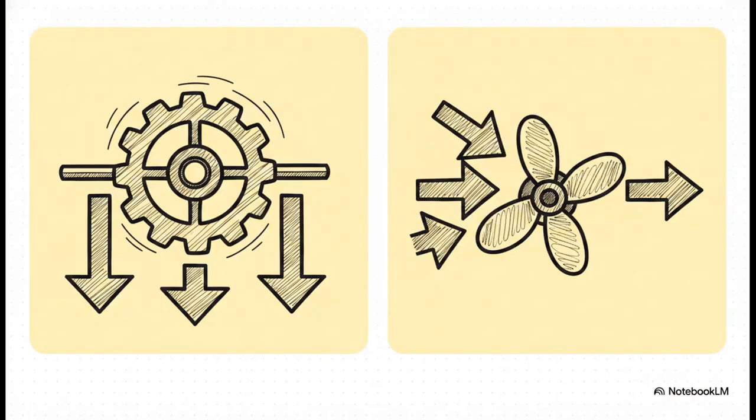Believe it or not, the physical chaos inside any machine basically boils down to two things. Most bearings fall into groups based entirely on their ability to handle two very specific loads. First, you have radial loads. These are forces applied perpendicular to the shaft, so think of the weight of a super heavy spinning gear pushing straight down. Then you have axial loads, which we also call thrust loads. These are forces applied parallel to the shaft, kind of like the forward push of a boat propeller. Every bearing is designed to handle one, the other, or a very specific mathematical combination of the two.